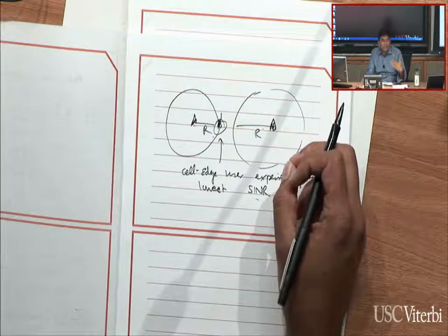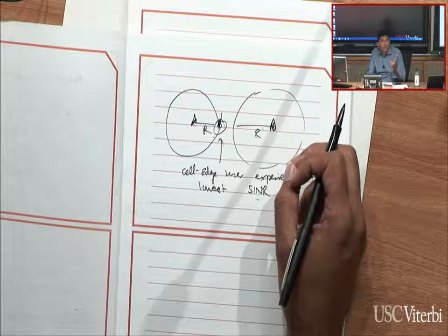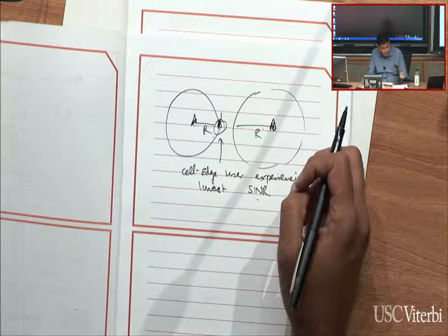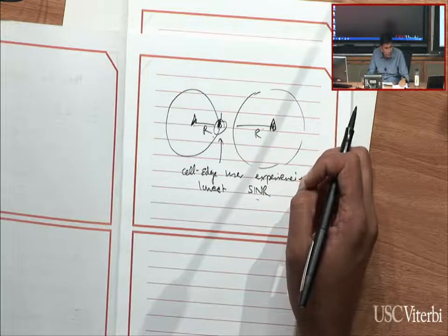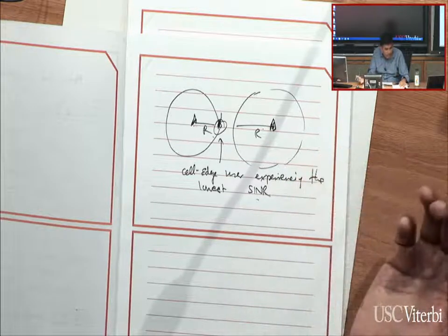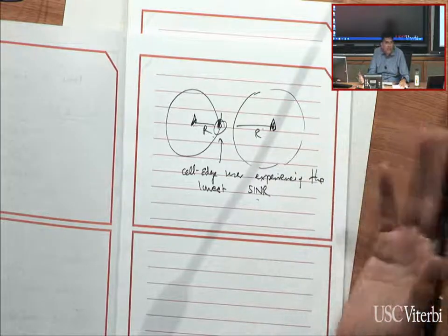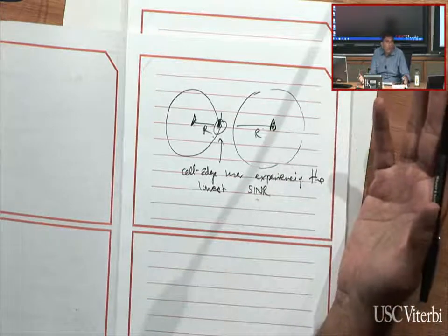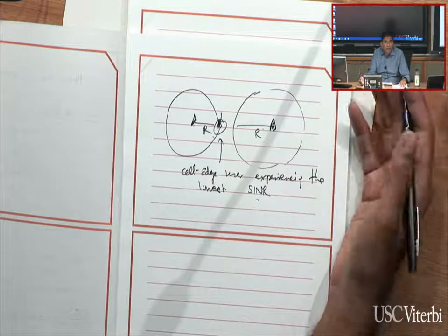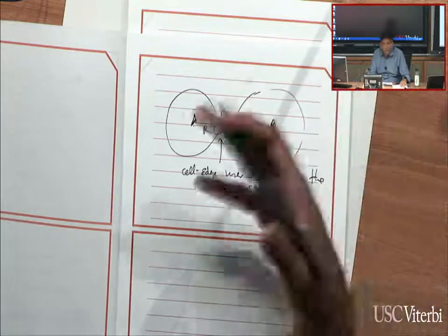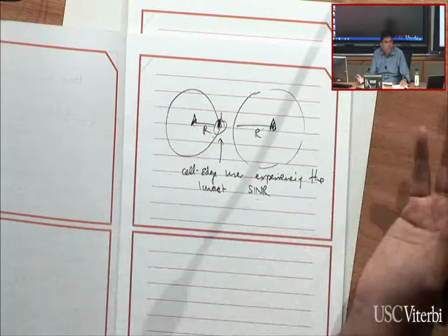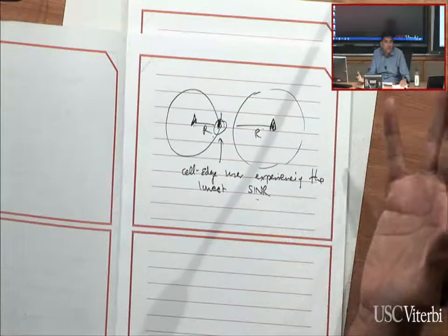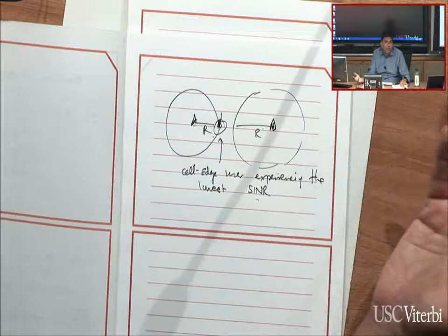I want to design my system not only to ensure that the bad events don't happen on average, but typically with some low threshold, right? And so in this case, I would want less than some probability P, maybe you want 1% chance that the SINR drops below acceptable values. Because if you're serving users, you're trying to collect revenue from them, you're running a business, and more than 1% of the time they're unable to communicate whenever they happen to be driving around near the cell edge, that's a bad design, right? And you wouldn't operate very long as a service provider if you had really lousy quality at the edge of your cells.